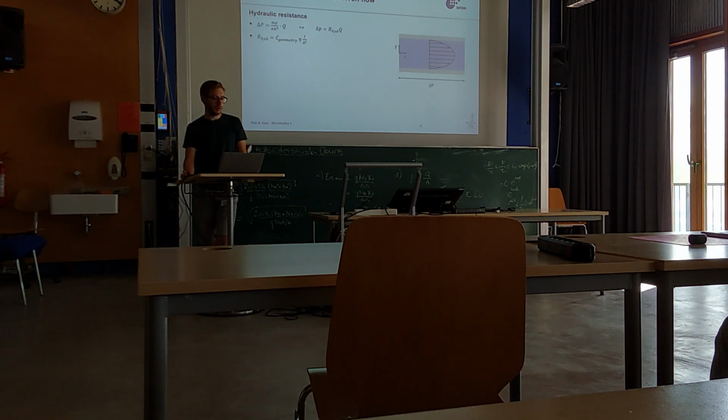And this hydrodynamic resistance is nothing else but a geometry factor multiplied by the viscosity of your fluid and the cross-section of the channel as well as the length. So this should also be already known from the modeling and simulation part, but this is mostly applied in this lecture and also in the exercise, so please